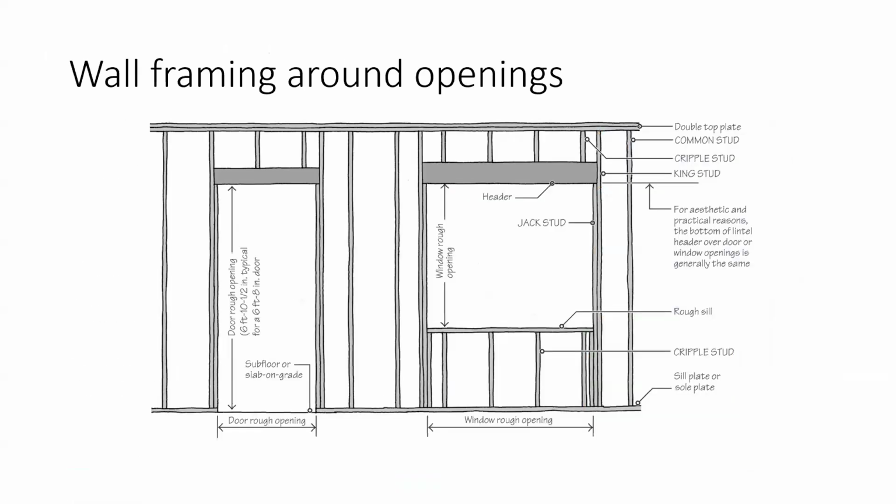So I already talked about all that. So let's talk about openings here. When they talk about the rough opening, that's not actually the same as the size of the actual window. So if you buy a window at Menards and you put your tape measure on it, it'll be 4 foot. But when you make the hole in the wall, you make it like 4 foot 0.5. That hole that you make in the wall is the rough opening.